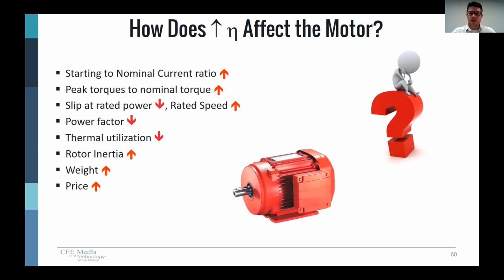Well, one of the other things you have to think about is that in an asynchronous motor, there are only two moving parts. It's two bearings and that's it. They're a very solid construction and it's a very simple machine and they last for a very long time. Larger motors can last up to 20 years. So in my opinion, it is worth it to have an increased efficiency motor in your system because of the lifetime of the motor. About 96% of the lifetime cost of an AC induction motor is the energy used just to run that motor.